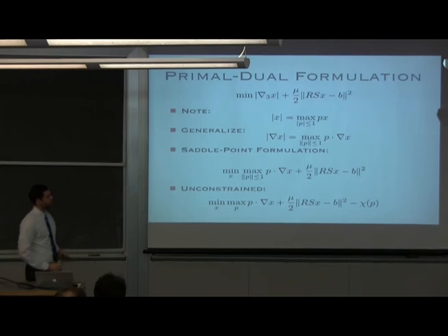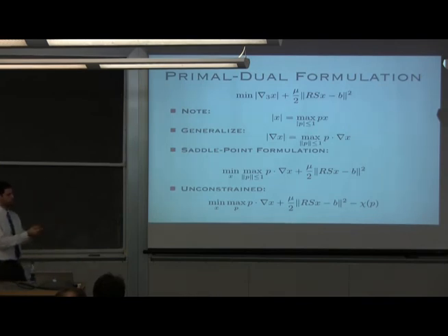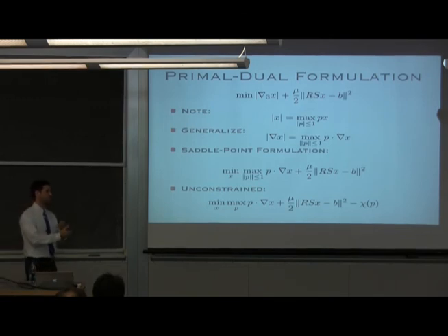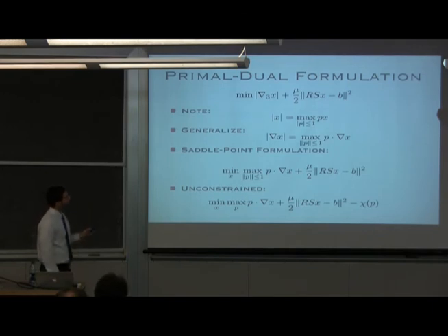Exactly. And on the FPGA, where we're doing a fixed point implementation, you don't have the luxury of adaptively choosing. You have to choose the constant, and you have to choose it in such a way that everything works out nice from the standpoint of integer arithmetic. But it turns out that choosing this constant is actually relatively easy.